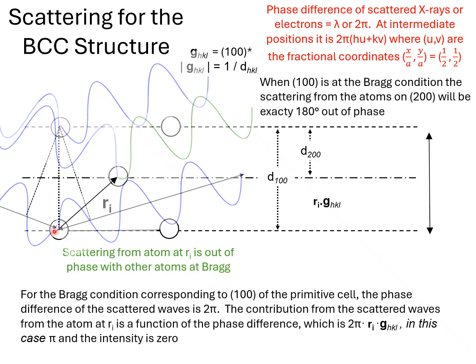That spacing, formally, you define it by taking the coordinates of the atom within the unit cell, defined by this cube. You take the coordinates of those atoms, and you take the dot product with the diffracting vector, when the diffracting vector is perpendicular to the plane and has a magnitude of 1 over d. So if we take the dot product, we get a real number and a reciprocal number, and we end up with a fraction. In this case, it would be a half.